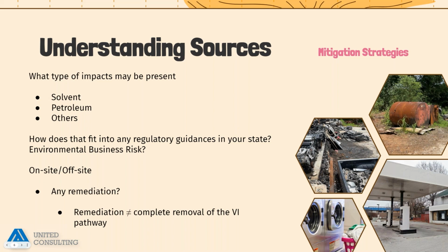In some cases, you can have groundwater impacts that do not pose a threat to vapor intrusion. Guidances from federal and several states provide separation distances for petroleum products in the absence of solvents or other commingled chemicals. They indicate that these petroleum compounds can readily biodegrade in the subsurface and not pose a hazard to vapor intrusion. Is that the case all the time? There are caveats to all these potentials, which United and Land Science can advise you on.